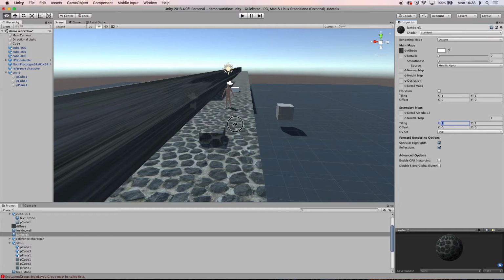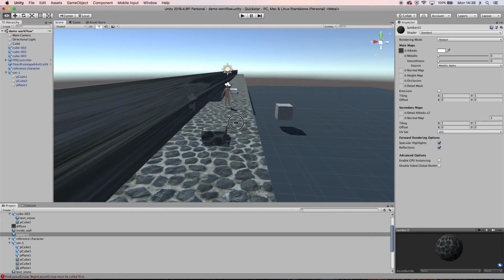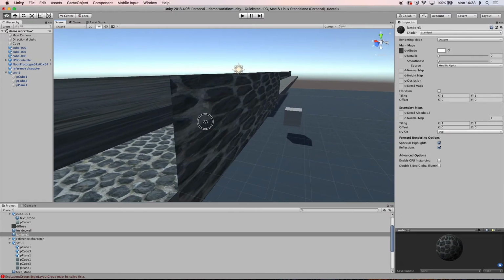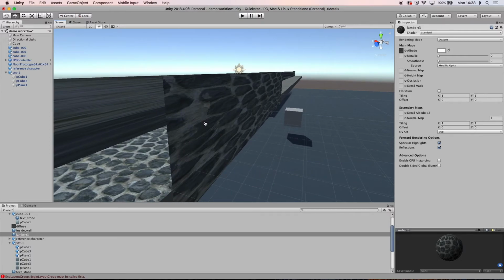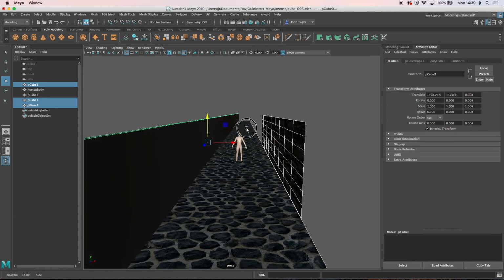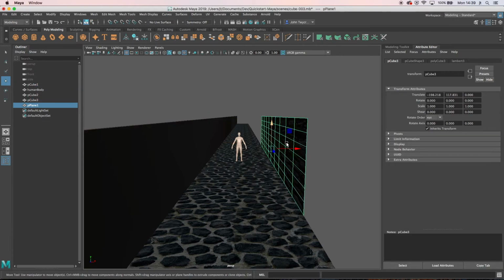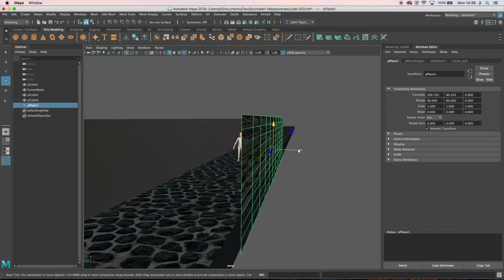But the main thing I now want to show you is about these normals, because that's not how I want it to look. I want it to look as if I can see through that on one aspect but not in another. So within Maya, any flat plane will have a normal aspect which will show, so where this red line showing, that's the direction you will see the image. So Maya's actually doing it on all aspects. But because we're working on cubes, this is always pointing to the outside. On a plane, it won't be working in that way.